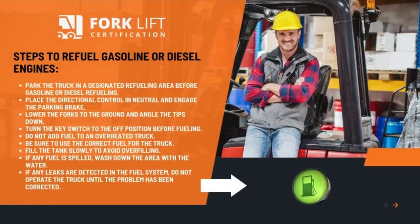Steps to refuel gasoline or diesel engines. Park the truck in a designated refueling area before gasoline or diesel refueling. Place the directional control in neutral and engage the parking brake. Lower the forks to the ground and angle the tips down. Turn the key switch to the off position before fueling.